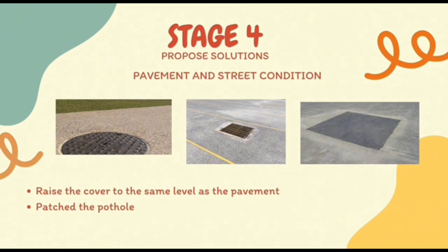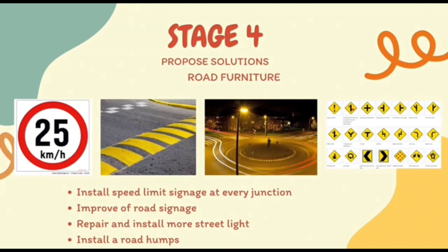from encountering unexpected bumps. To resolve the drainage problem, the drainage system should be improved to prevent water pooling. To tackle the road furniture issue, we propose installing speed limit signs at every junction to inform drivers of the appropriate speed for the roundabout.